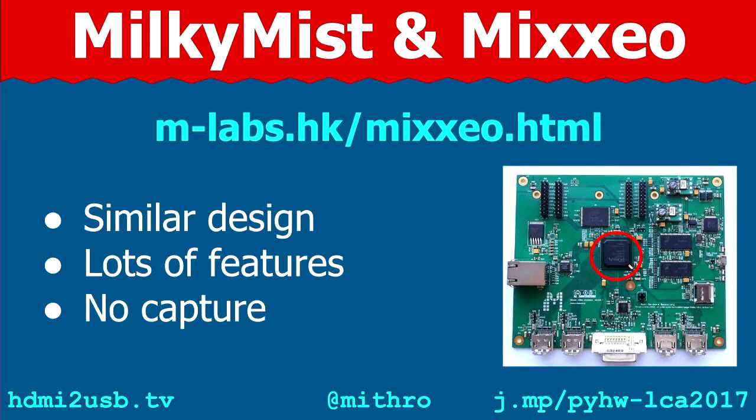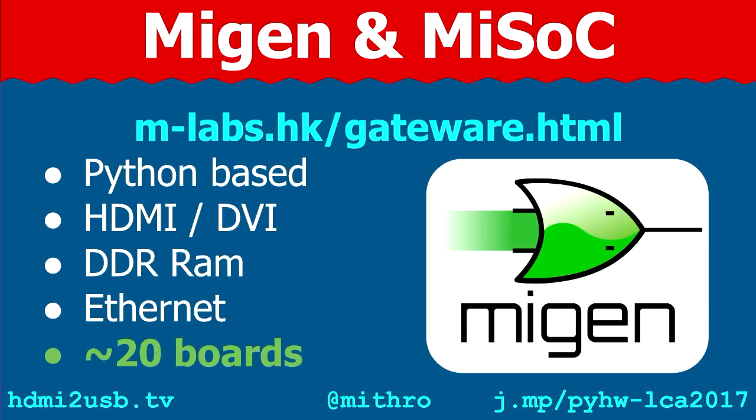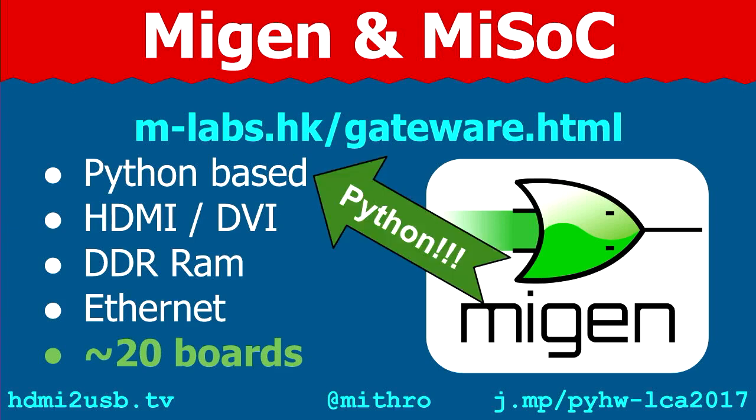Then I came across this thing. This thing's called the Mimas. It has a very, very similar design to our board. Doesn't do capture, though. The interesting thing is that the people who had developed that had written a system for describing the hardware on it called MiGen, and it already had a lot of components we wanted, like HDMI, DVI, DDR, and Ethernet, and it supported a lot of boards already, and it was Python-based.